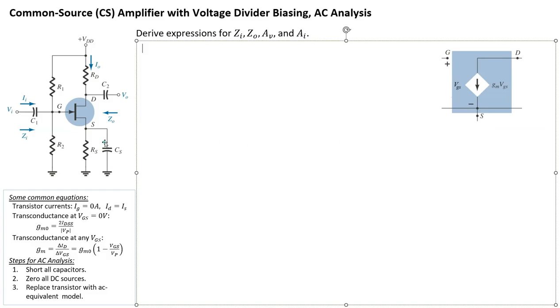Let's have a look on the right hand side. So remember that CS and C2 are both going to be short. So when CS is shorted, RS is going to be bypassed. Another name for this particular capacitor is a bypass capacitor, or shunt capacitor. So the idea is, because at the frequency of interest this is a short, currents will just flow through CS instead of RS. So therefore RS will not have any effect.